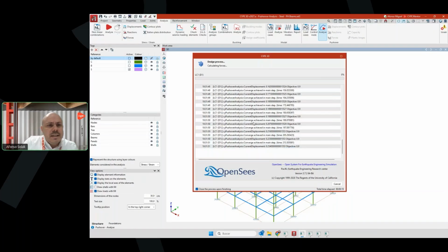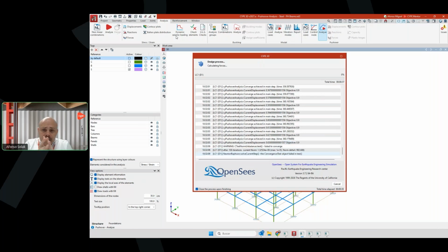You can see that this button here from my stress and strain analysis is available because I considered the seismic loads in my project. And then we can see how the spectrum will cross with the pushover curve, okay? So this is an analysis that will take a little bit of time here. Let's leave it here for a while, okay?